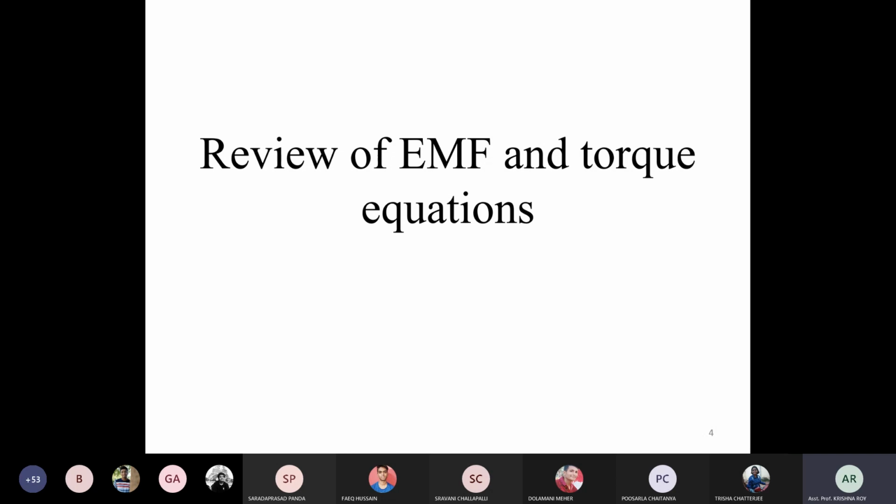So when electrical power is given to its armature winding, which is normally placed on the rotating part, that is the rotor of the machine, then at that moment we need to excite the field winding also to create the field poles, that means the magnetic flux. Normally electromagnets are used. If we use permanent magnets for smaller machines, then there will be no requirement for the excitation to the field winding. Actually there will be no field winding if we use permanent magnets. But permanent magnets are used only for small machines.